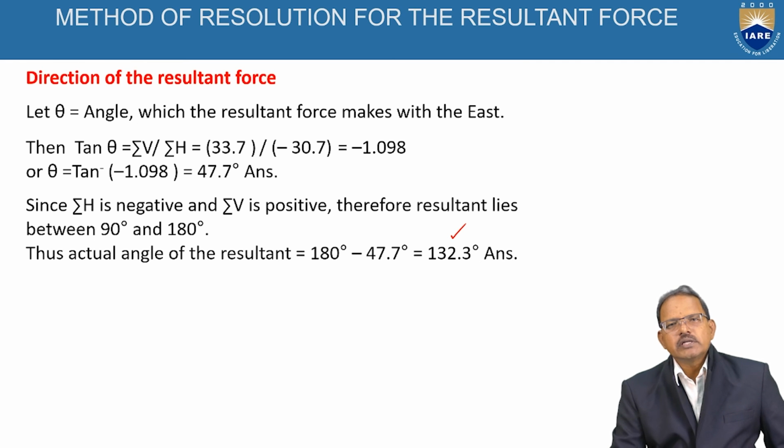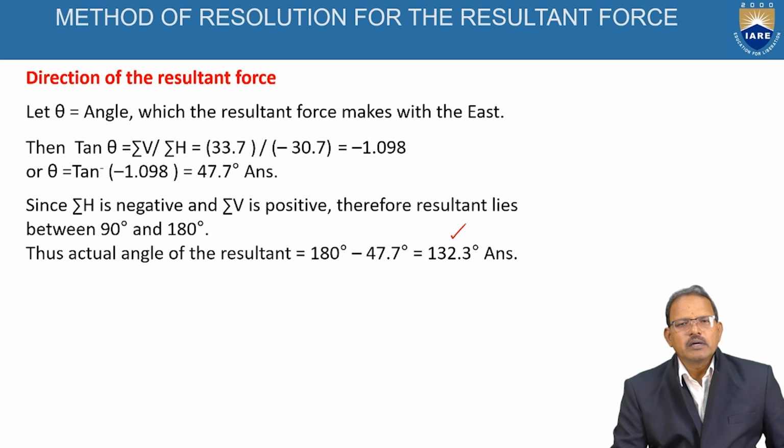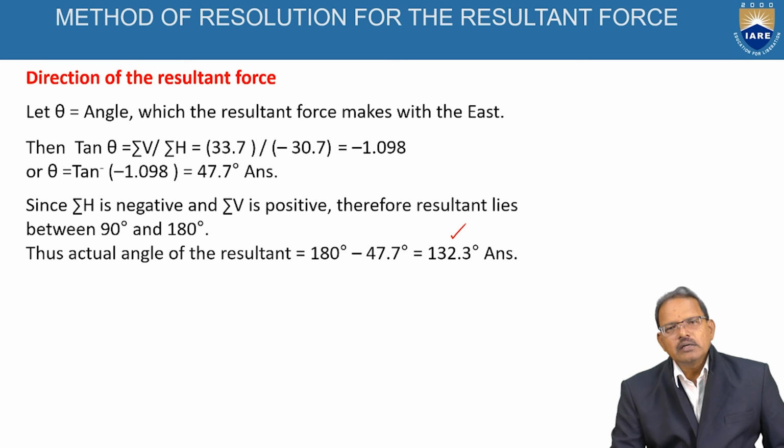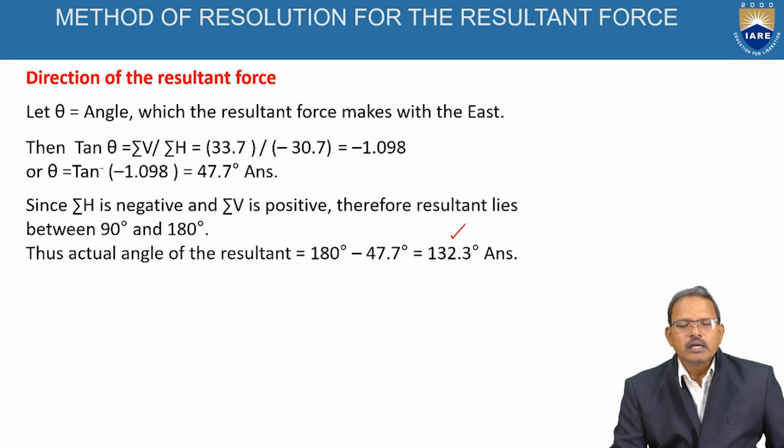When several forces are acting on a body, graphically the resultant can be determined by using the law of polygonal forces. According to the law of polygonal forces, when several forces acting on a body are represented both in magnitude and direction by the sides of a polygon taken in order, then the closing side of the polygon gives the resultant of all the forces both in magnitude and direction, but acting in the opposite order.